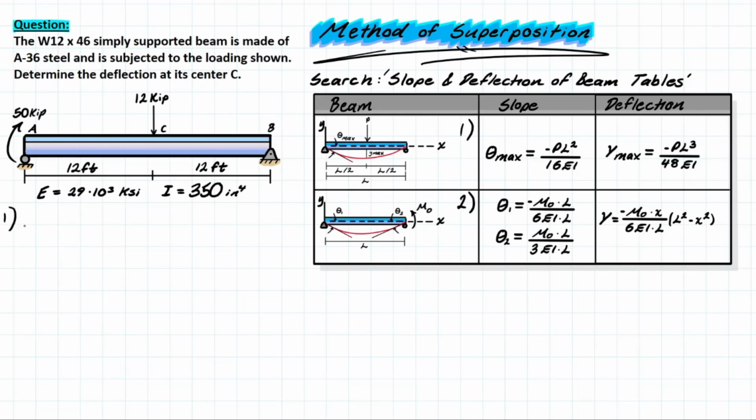I'm going to look at loading case 1, and we're getting the max deflection because it's at the midspan. And we have the numbers that look like this. We're plugging into this formula here. We have negative 12 kip, and then the length of the member. So 12 plus 12 is going to be 24 foot, cubed. And then we put that all over 48 EI. That's going to give us 3456 kip foot cubed over EI. Going downwards, obviously.